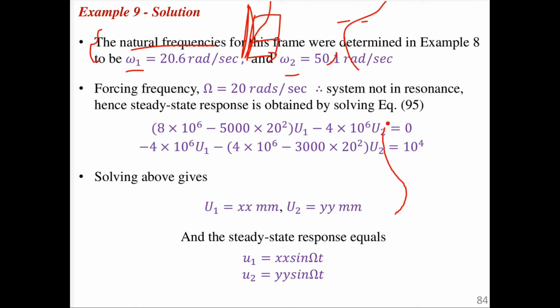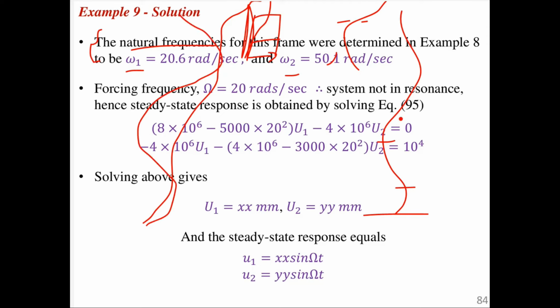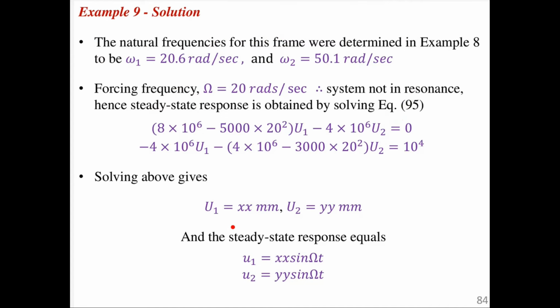Then you are going to see how, because this tells you the shape of the structure due to vibration at different stories. Different stories meaning different degrees of freedom, different modes. The first vibration that will occur, maybe all the floors will be displaced on the same side. The second frequency, due to motion on the second floor level, brings about a different kind of shape, maybe something like this. So you need to practice with the examples that I gave you.